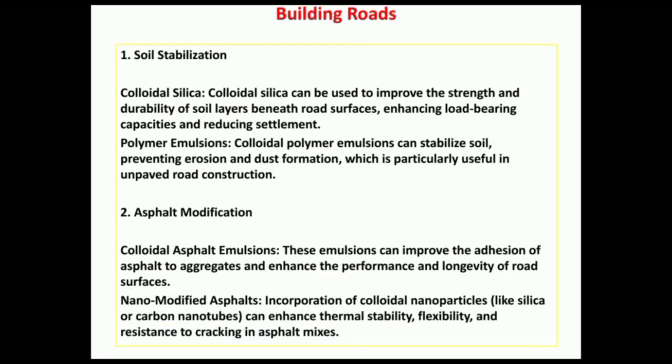Colloids play an important role in various aspects of road construction and maintenance. Colloidal silica can be used to improve the strength and durability of soil layers. Colloidal polymer emulsions can stabilize the soil, preventing erosion and dust formation, which is particularly useful in unpaved road construction.